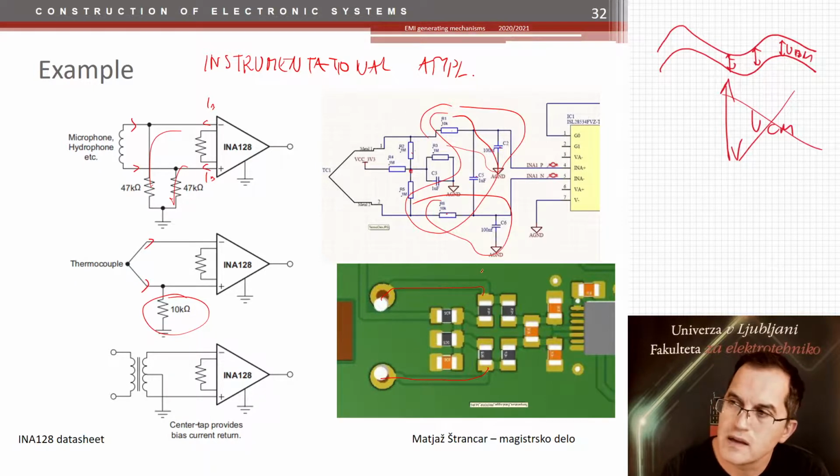Everything is symmetrical, including the values of resistors and capacitances, but also the placement of these components, in order to make the design equal for the left and right part. So these two stray elements towards whatever there is are the same.